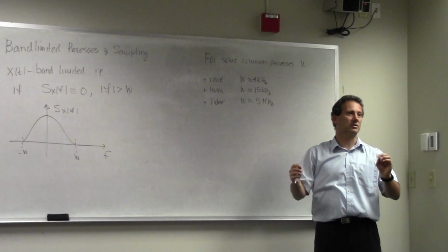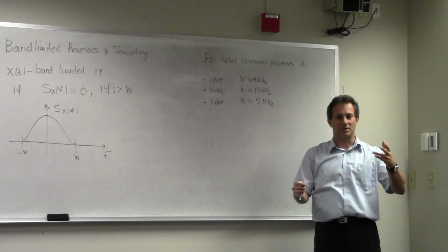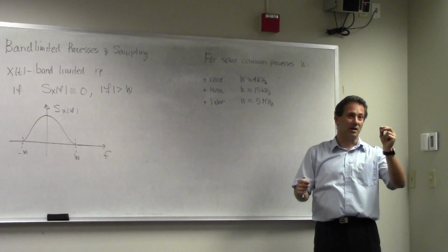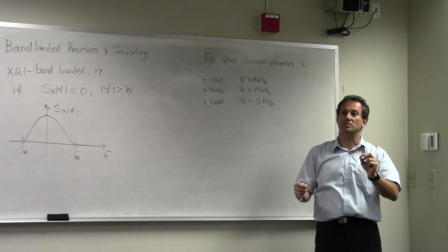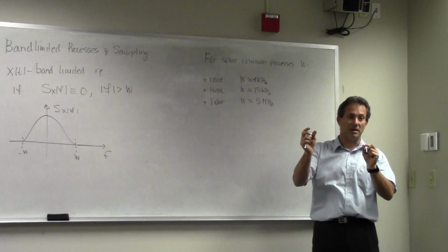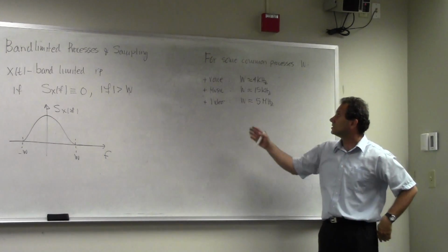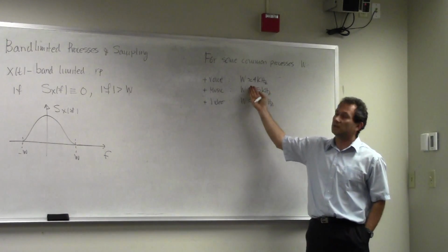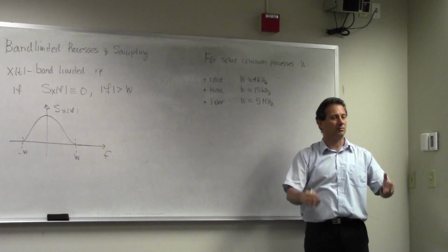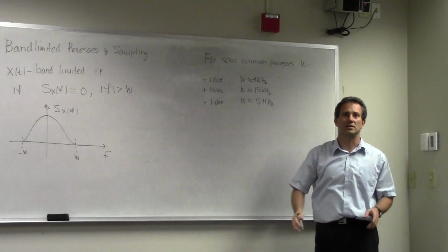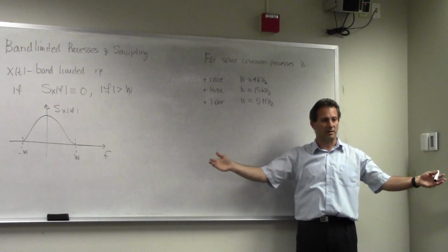Now, there is still some difference. When you talk to somebody on the phone and they ask you what your name is, you have to say N like Nancy or C like Charlie, because some of the legibility is lost, embedded in these high frequency components that we cut out above 4 kilohertz. This was done in the early communication systems because we didn't have that much bandwidth, and we tried to squeeze everything we could out of the copper line and multiplex signals.